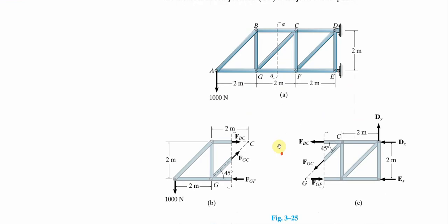After making the cut, we have something like this. Now, mind you, if we make a cut, the forces along this component, if pointing in this direction, then if we're looking at it from the other direction, it will be pointing in the other direction, just like our shear force too. Now, looking at this, we first determine the forces DX, DY, and EX first. After doing that, we'll be able to resolve this particular component.